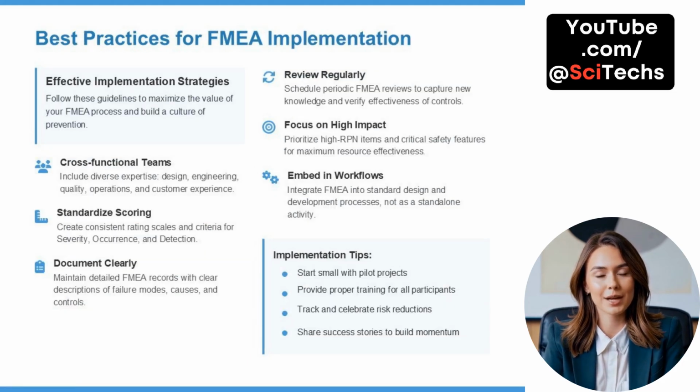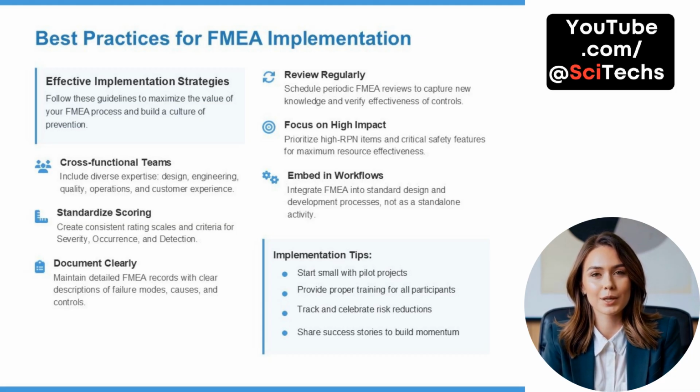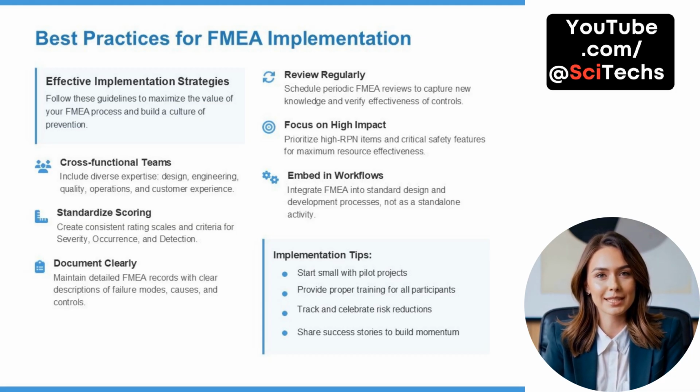Best practices for FMEA implementation. To maximize the value of FMEA, organizations should follow a set of best practices. Begin with a strong cross-functional team, drawing expertise from design, engineering, quality, operations, and even customer experience. Each perspective adds unique insights into potential risks. Standardize your scoring system to ensure consistent severity, occurrence, and detection ratings across teams and projects.